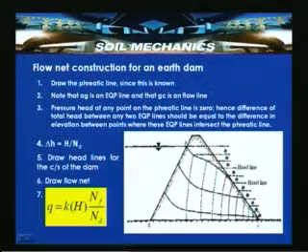Thereafter, we tried to discuss how the rate of flow can be estimated through an earthen dam. For that, we discussed three methods: Dupuit's solution, Schaffernak's solution, and Casagrande's solution, where the main impetus is to locate the phreatic surface, and thereafter the procedure is very simple for determining the rate of seepage through the earthen dam. One concept to keep in mind is that the pressure along the phreatic line is 0. So, the total elevation divided by the number of potential drops makes it easy to draw equipotential lines. The same concept can be used for determining the rate of seepage through this medium, having a homogeneous soil with isotropic permeability K.